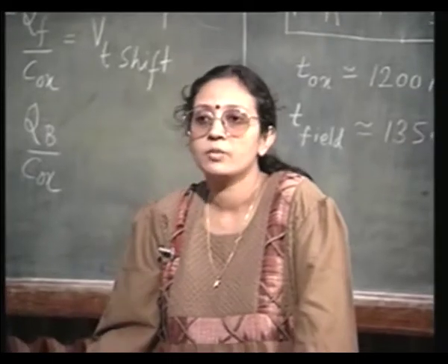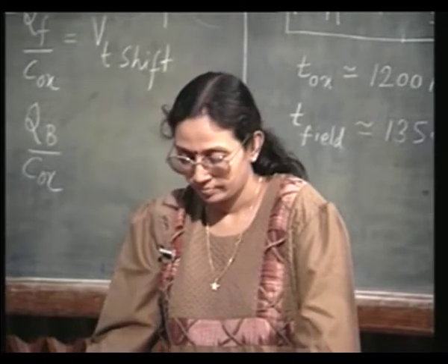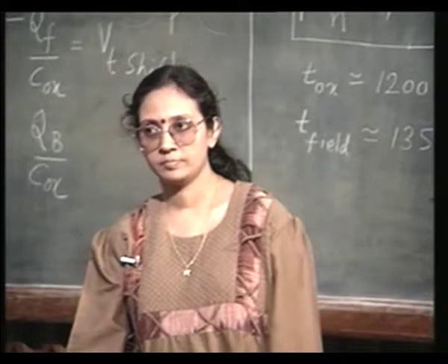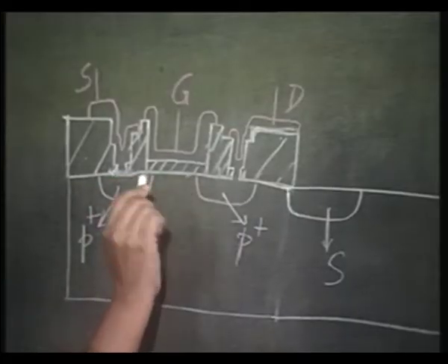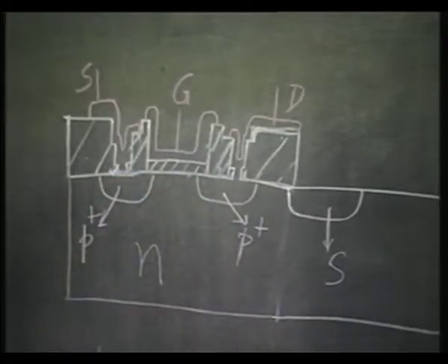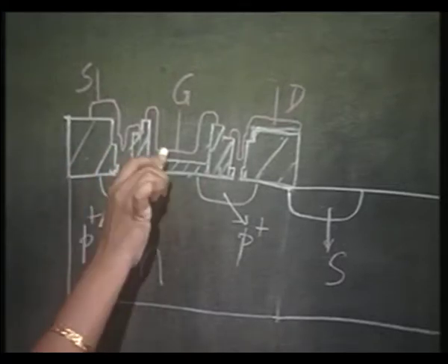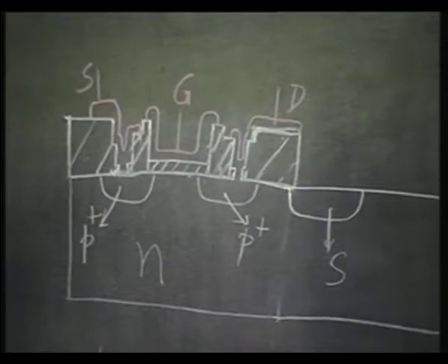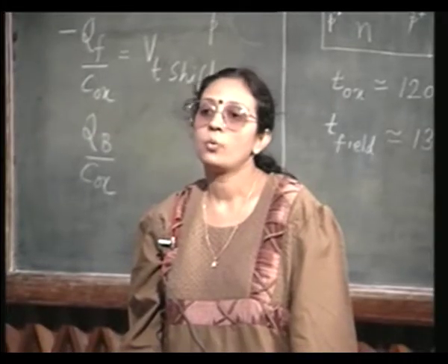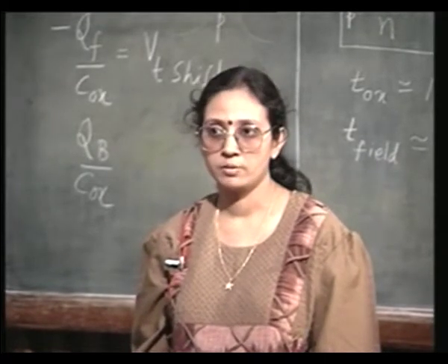The other problem is of course more important, and that is the overhang capacitance. So, this overlap will create a problem both as far as area is concerned. As you go to smaller and smaller dimension devices, you want to save more and more area. This is proving to be the bottleneck. The second thing is that gate to source or gate to drain overlap capacitance. So, we needed a technology where the gate will be automatically aligned to the source and drain.